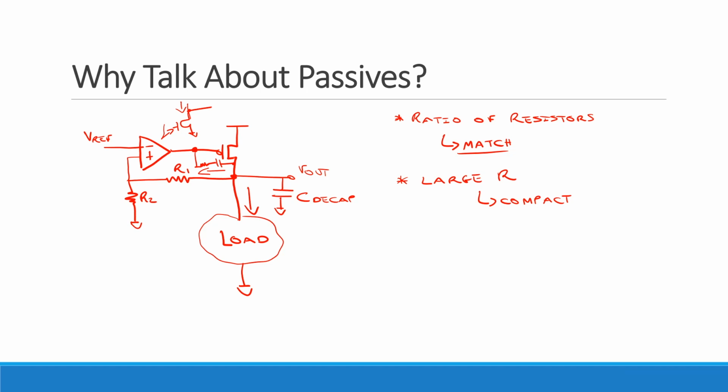So in that compensation network, what's important about the resistor? You want to make that R in the compensation, let's call it RC over here, equal to roughly 1 over GM, right? Well, guess what? 1 over GM has to do with transistors. R has to do with physics, right? Kind of resistivity and materials and things like that. So if I was to really do this in SPICE, I believe you that you could tweak that R to get it exactly to be 1 over GM.